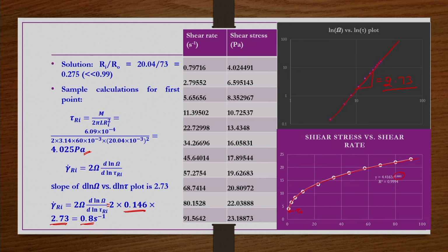So, now we have done an example problem also, showing how to use the equations of a concentric cylinders rheometer to obtain the rheological behavior of any given fluid, if you know the rotational velocity versus torque information from the experimental data.